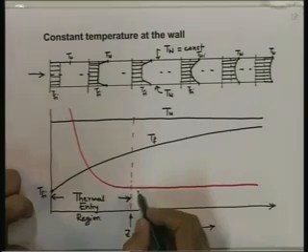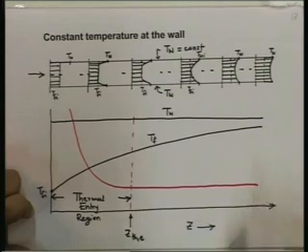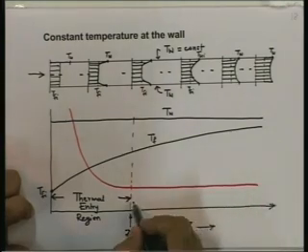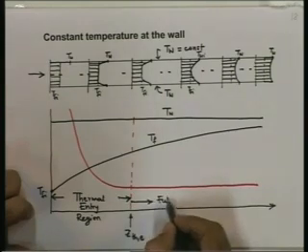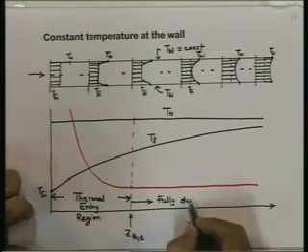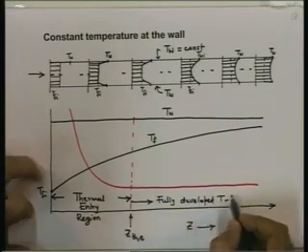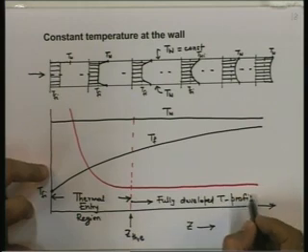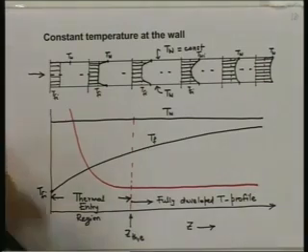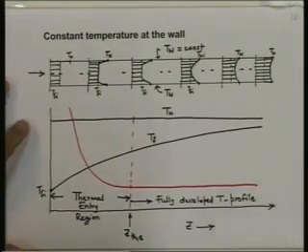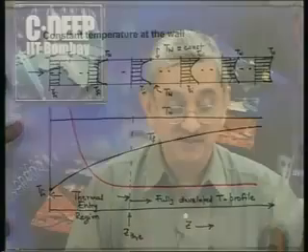Beyond that, although the temperature of the fluid keeps on increasing, the heat transfer coefficient doesn't significantly change. So from this point onwards is a zone of fully developed temperature profile. We will look at what is exactly meant by fully developed temperature profile slightly later. We will define it properly.